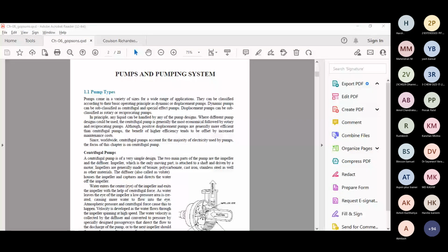That's why we see motor efficiency is 85%, right? So all the electrical energy that we are passing to the motor is not getting conveyed to the pump shaft. That is the loss because of the motors. You would have seen that in pump motors, the motors get heated up. That is all because of the dissipation, because of the coils inside. That's why we have given fins on the surface of the motor, right?